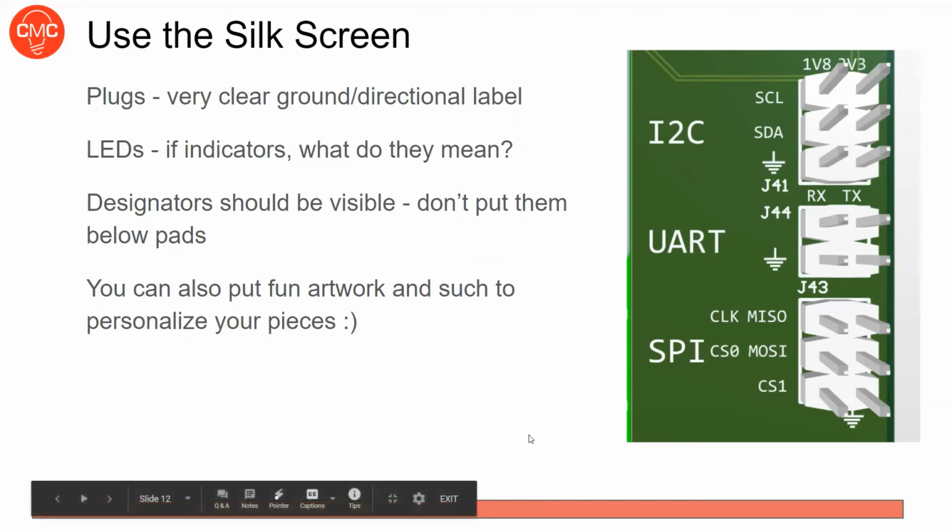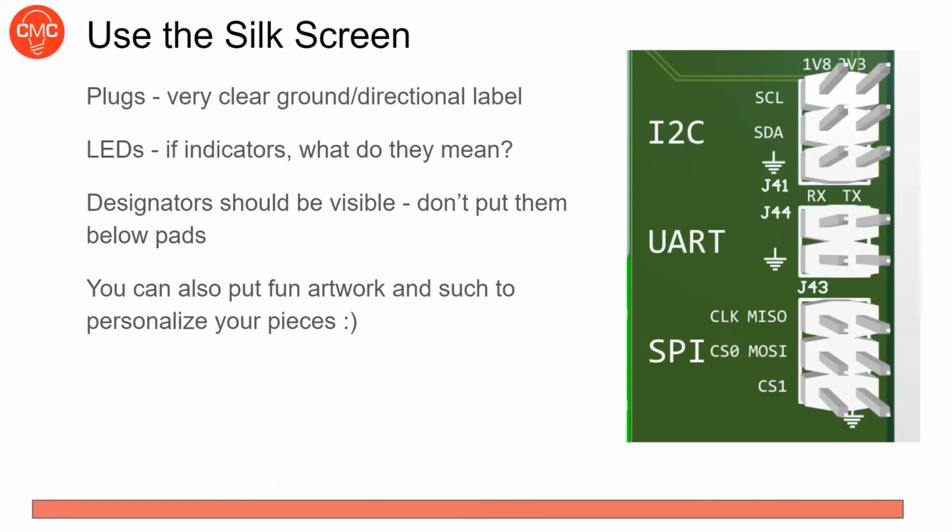If it's a switch, I didn't do this on the board that I gave you guys. I should have. I did not label which side of the switch was on and off, which is just stupid. So when you make your boards, label which side is on and which side is off, because then you can actually not have to plug the battery in and have it start playing. You plug the battery in when it's off and then turn it on. Sorry about that. I did not do that. Shame on me. But you will do it. You will be better than me.